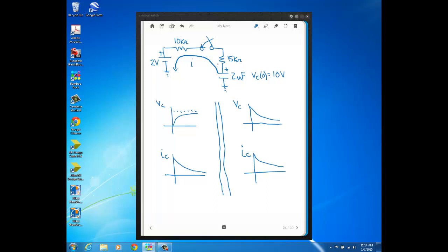So you see this problem is different than any of the previous problems because here you have a discharging case where in the discharge path there's a source along with the resistor. In the previous video we had a discharge case where there was just resistance in the discharge path, and in that case all the stored energy was depleted and dissipated as heat, and the final voltage, the steady state voltage for the discharged capacitor, was 0 volts.